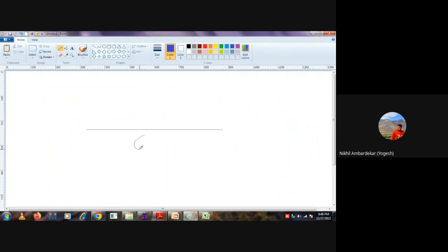Span is 6.6, our span. Diameter by 2. 3 kilonewton. Actually, on the walkway we can consider 1 kilonewton also, because it's a walkway. It's not like a living room or kitchen, because it's a very limited space and only once in a while will it be loaded fully. But okay, no problem.